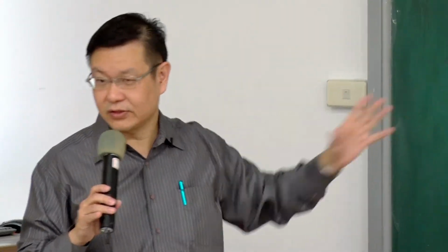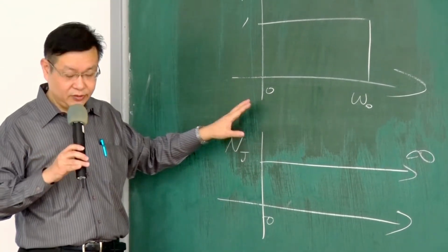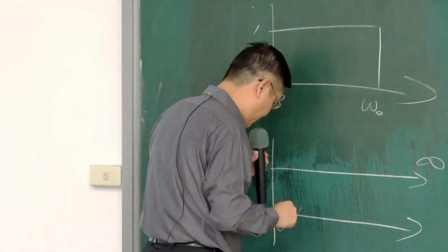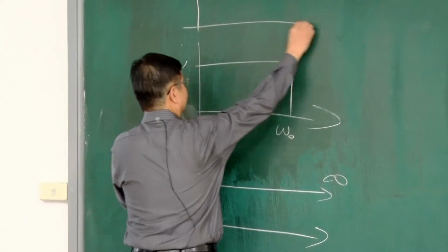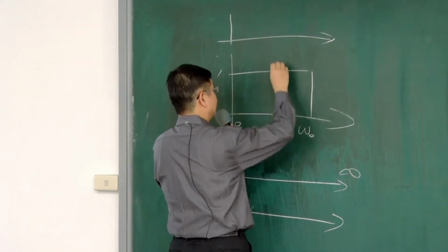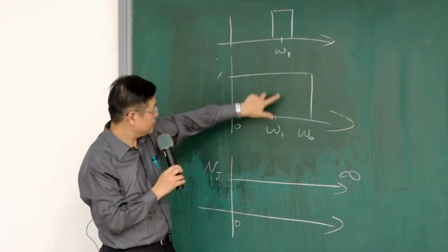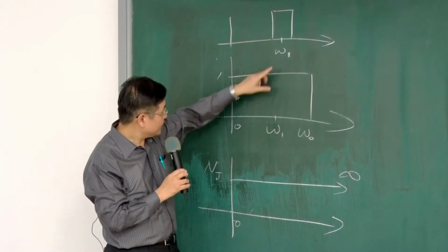Okay, this is a typical problem. If you want to design a very high frequency response sensor, usually you will also suffer from high noise because you open a large window. That's why, when operating at high frequency with some very high sensitivity sensor, we will consider not opening up the window that wide. We'll consider using some kind of filter to filter our signal. So through a filter, for example, if your operation range is not in this range, maybe in some range like omega 1, we open up a window with the filter in only this range. So now the window will become smaller.